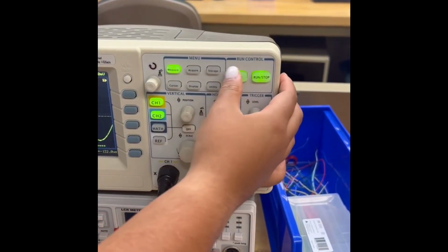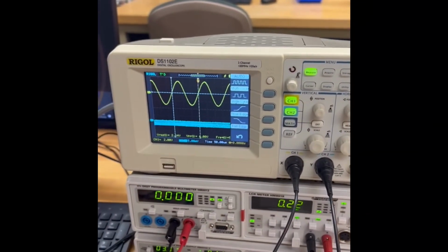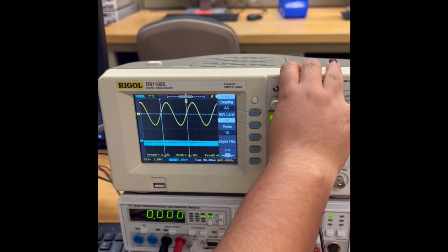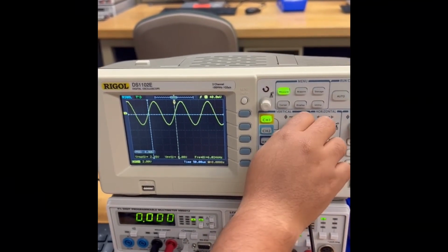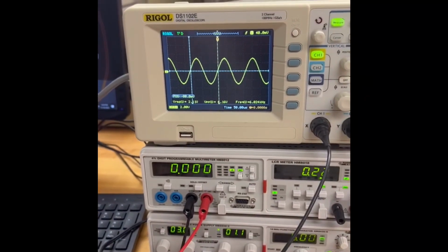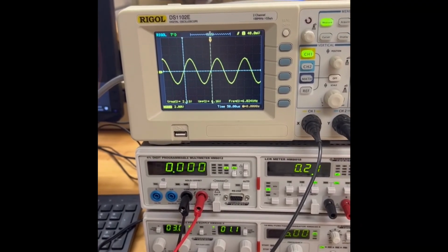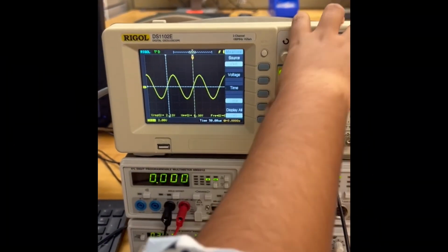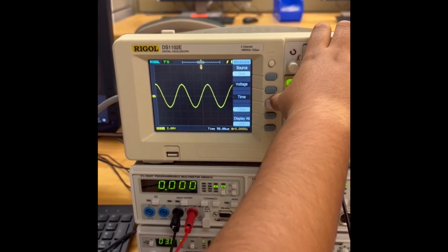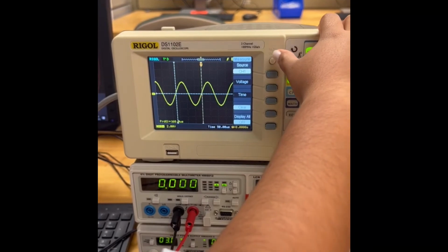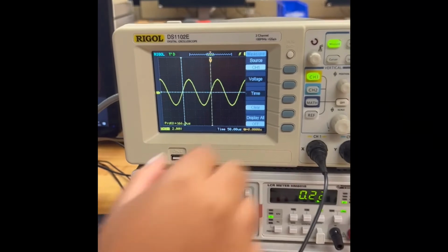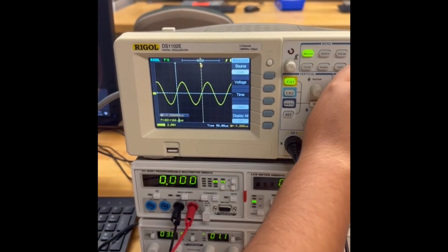Once the oscilloscope is on, we're going to let it run on auto to let it refresh. We're going to go ahead and turn off channel 2 because we are not using channel 2 at the moment. We're focusing on channel 1. We're going to go ahead and scale in our channel 1. And we're going to first measure our period time. We're going to click on time, then period, and that is going to give us 1.66 microseconds for our new school recording.